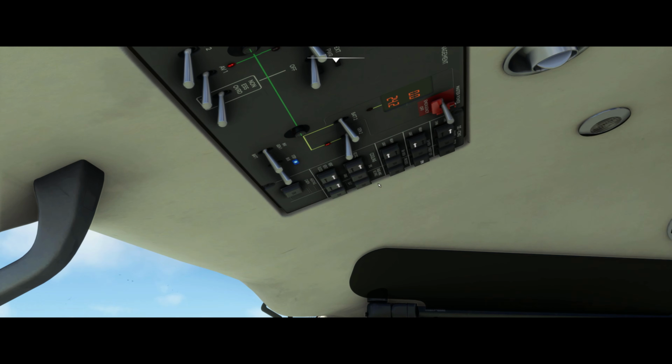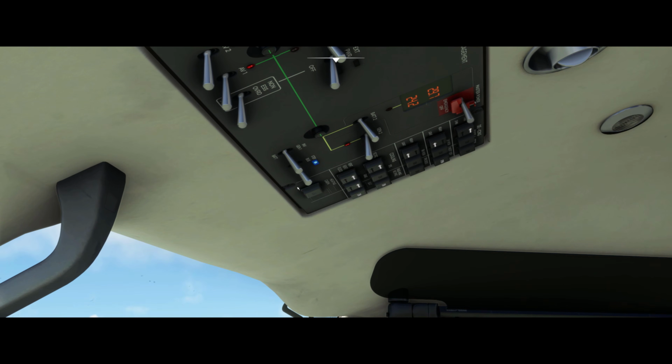And then down here to the cooling system, I want the system off. I can pre-select how I'm going to run this if I want to at this point, so I can turn on the VCCS, which is the air conditioning in the airplane if I want, or just leave it on recirc, and I can select vent or vent plus flood, high or low, etc. But the main thing that I'm checking for at this point is just to make sure that that system is off for the start. And then I would turn on my no smoking and seatbelt signs right there, and then make sure my cabin heating is off.